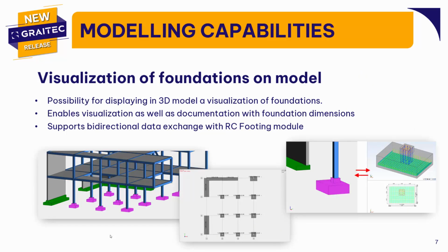Now you can visualize the foundations in the main structural model. So we have added this tool. It has some benefits, as you see here. Now it's possible to see them in your 3D visualization and in the viewpoints. When you're creating your documentation with foundation dimensions, you will see the foundation dimensions in the documents, etc. And also, it supports the exchange with the RC footing modules, so you can select this foundation object and send it to the foundation module of Advanced Design.